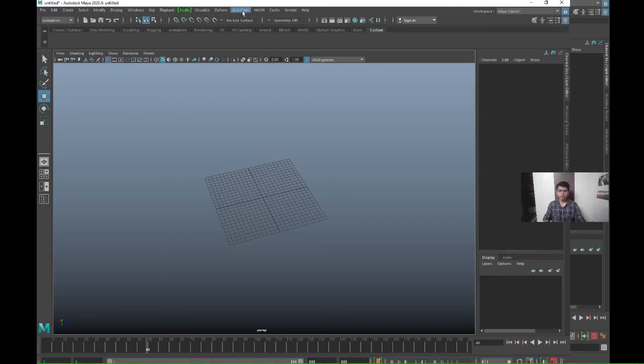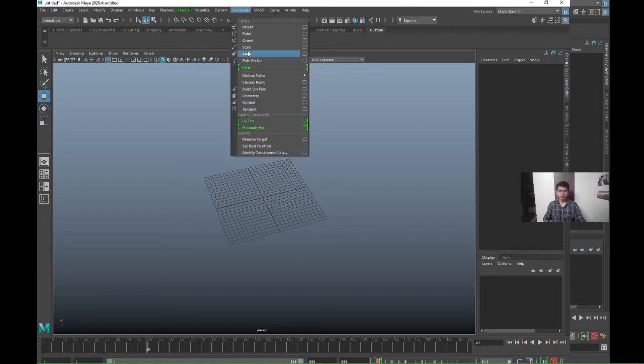So this is how: just click on whatever option you want a shortcut for. Here, if you see, there is nothing, this is totally empty. Now this is the option. Suppose I want parent constraint in the shortcut, then I'll hold Control and Shift, both together, and then left click the mouse on the option you want. See, now you got the option here, where my cursor is.